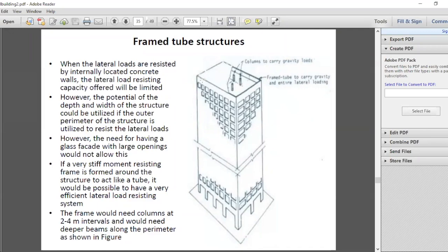And this shear lag effect comes in here as well, because it's a fairly large building, something like 40 meters by 50 meters. So when the structure deforms laterally, we cannot expect it to keep the shape perfectly. So there will be variations in the shape. And because of that, although we have a very wide flange, which can actually effectively contribute, it will not contribute fully. So that is one of the drawbacks.